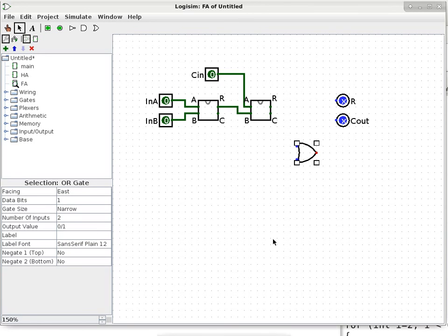We have some loose connections here. Okay. How do we deal with the loose connections? We have 3 outputs, a disjunction, and 2 actual pins as outputs. How do we make all these connections? The result of the second half adder, where does it go? It's the result of the entire full adder. So that just goes to the R pin here.